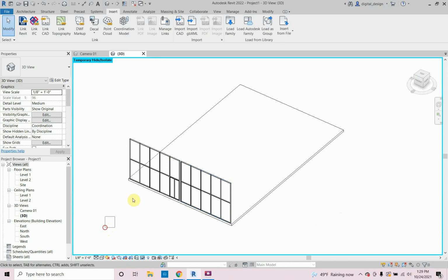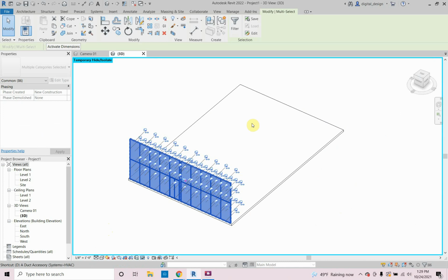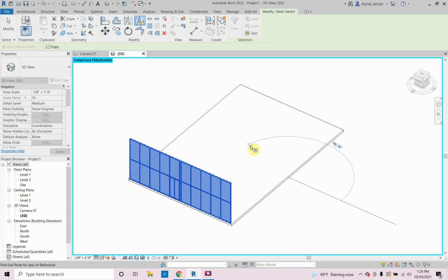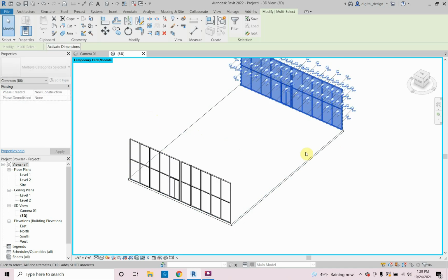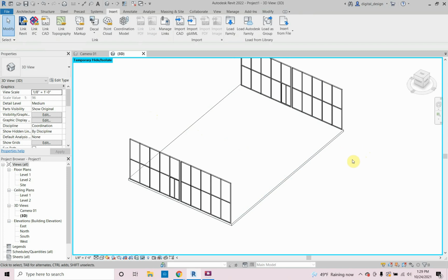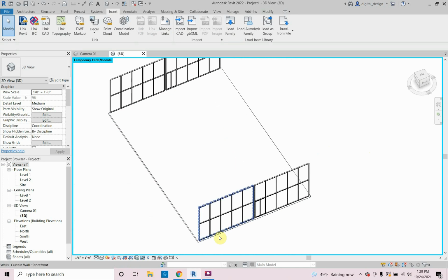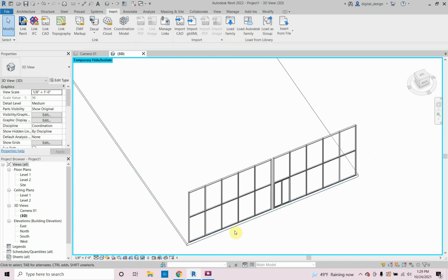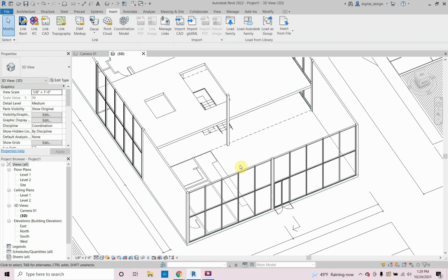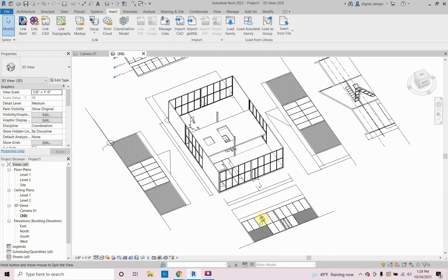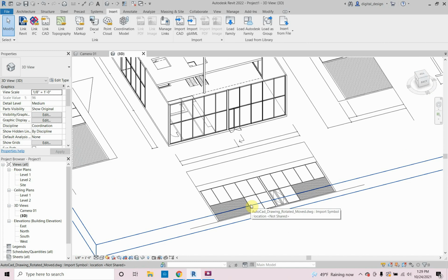So now I can make a window selection, type in DM, find the midpoint here, and then just go across to the other side. Make sure it's horizontal, or hold down the Shift key, which gets rid of the blue line, which I don't like, but the Shift key works. Okay, so now we've mirrored that to the other side. If I type in HR, it brings back my objects. So the shortcut is hide reset, HR.